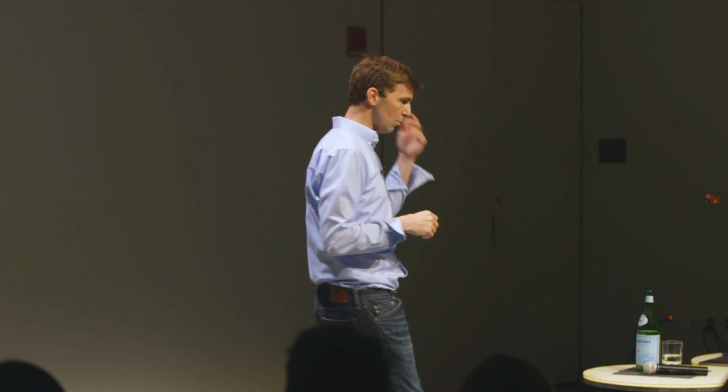And within this, we can also make these parallel devices. We can make mechanisms by folding. And so that's a very simple concept, but the implementation of it is basically if I have rigid materials surrounding a compliant material, that compliant material then describes a fold, describes a weakened region that we can then array however we want throughout this device and then create these linkage mechanisms which then can create arbitrary degrees of freedom. So I can get anything, think back to the most complex pop-up book mechanism that you've ever seen. We can do that, but we can do that now at arbitrary scales, to very small, even smaller than what I'm showing you, to arbitrarily large if you'd want, although there's better ways to do things at larger scales.